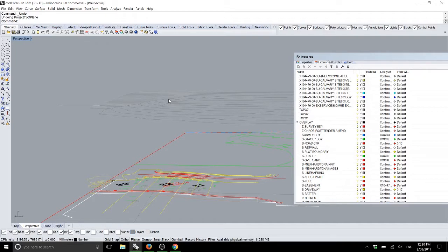If they send you contours and they don't have numbers, which way is this going? We know its steepness, we know the slope, but is it going down? Are we looking at a trough, or are we looking at a hill? Do you know? Could this be this, or could it be that? You can't tell, right? And the other thing is, this particular contour drawing is showing you this. How tall is the hill? You don't know, right? You can only assume that information. That's the only information we know. Any information other than that is assumed.